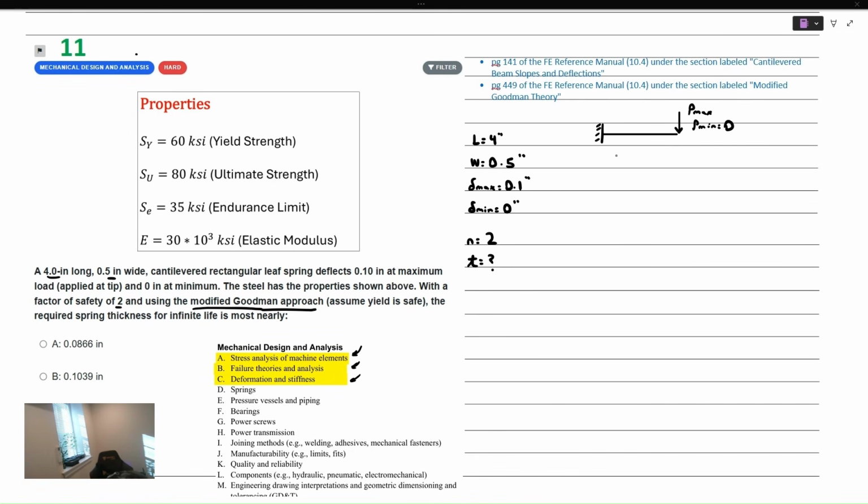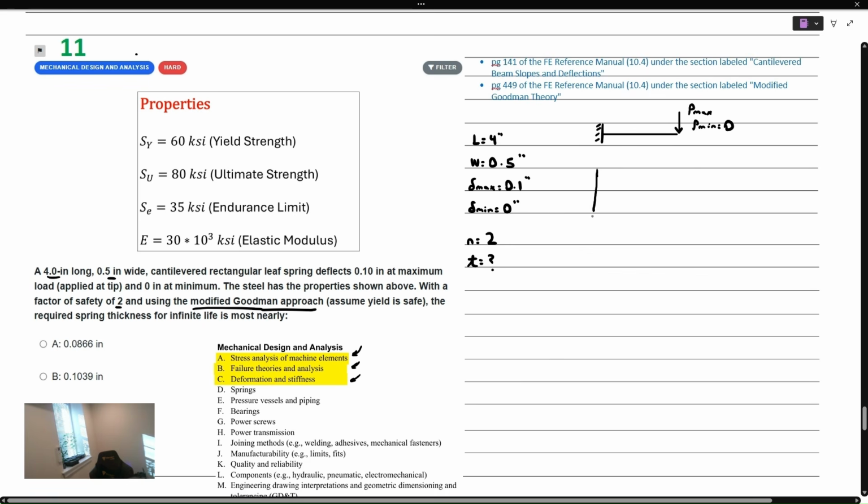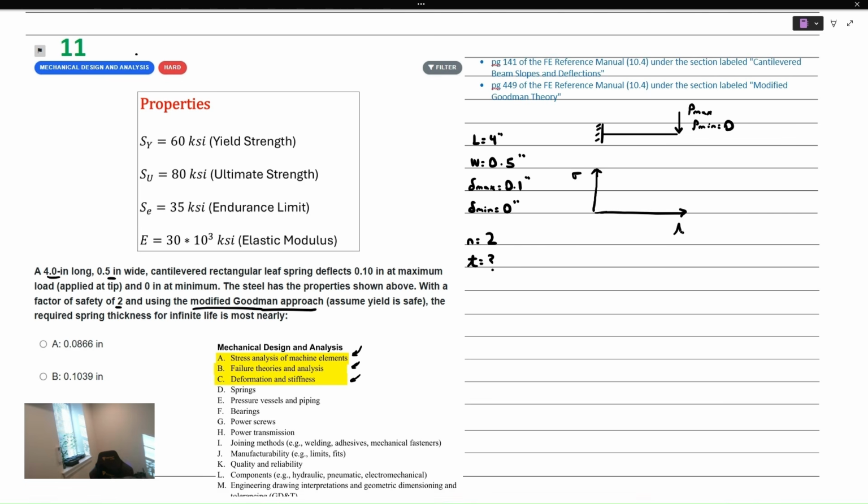I'd like to start off reviewing the idea of fatigue. And when we think about fatigue here, just the phenomenon is associated with variable loading. So if we draw a stress history here, let's say we have a 0 valued mean stress. The mean stress is equal to 0, and the alternating stress is less than the yield strength. We would have a plot kind of like this. It's a sinusoid representing the loading, and we call this loading scenario fully reversed. That's because the max and the min are equal but opposite here.